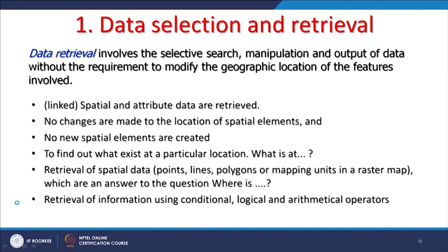Now for this retrieval, you might have seen the map calculator, for example in ArcGIS, or simply the query builder in different GIS software. What you would find is that they allow us to use various operators. What are those operators? Conditional, like if this is greater than this, then select.